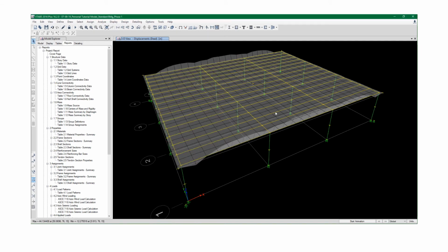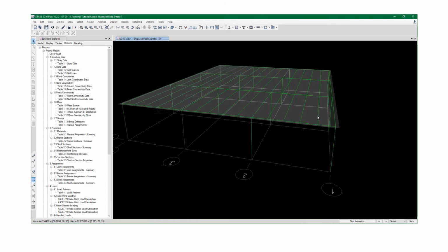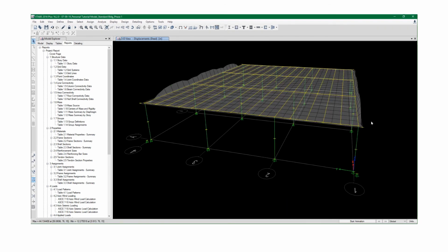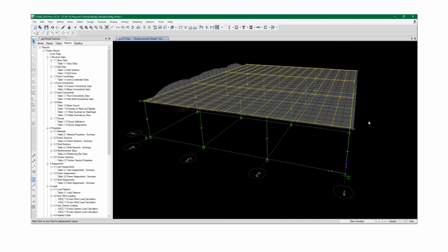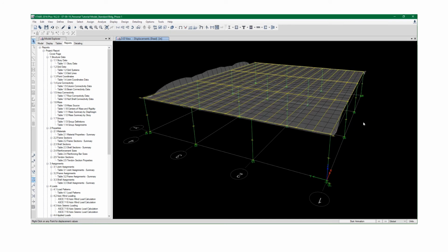It's along the edges. Some funny business that happened after we created the envelope. All right, so once we created the cladding, things kind of went haywire because there's some meshing that happens with the cladding elements just as well. All right, but we're good. So it doesn't affect the lateral frame analysis, and as an engineer, you have to understand that. Let's save the analysis, and that's it. Video completes.